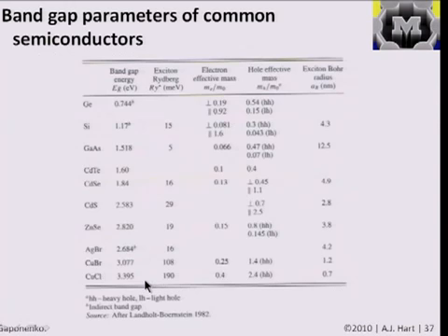And a lot of bulk materials have band gaps, basically because metals have a lot of free conduction electrons. They have zero band gap in their conductors, but semiconductors, because of the way their electronic structure develops, have finite band gap energies. And when we take the case of a semiconducting nanoparticle, because of the effect of the size on the band structure, the band gap of the material effectively depends on the size.